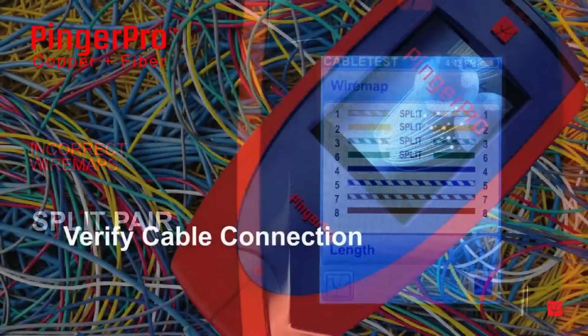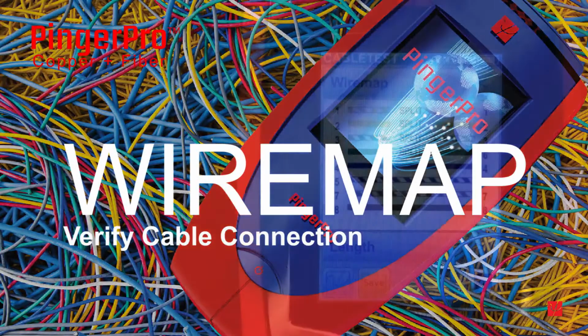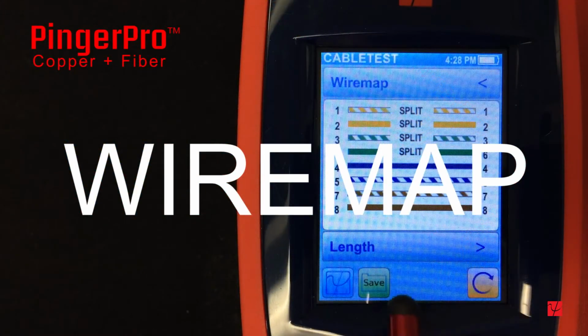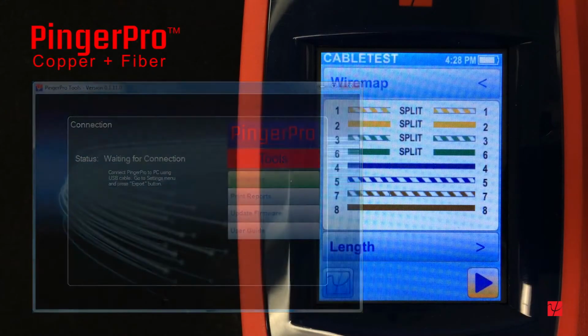Verifying that a cable has been connected properly is a basic network task that can be accomplished easily with the wire map feature of the PingerPro. When you have completed a wire map test, press the Save button to store the data. The data can be recalled later for review or exported to the PingerPro tools to document the test results.